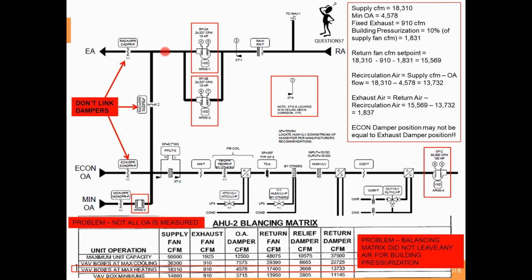You're using that as real-time feedback for these return fans. Loop tuning of these return fans is really critical. It's a challenge to do that. I'm going to say that's probably the least favorite of all my ways to do this.